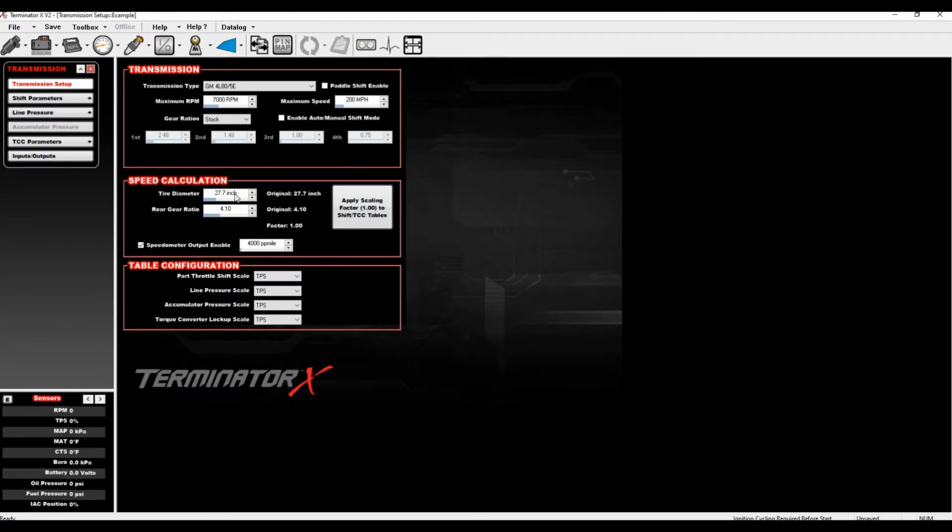So a 275/60, if you multiplied that by 0.6, or it's really 60% of the 275 width of the tire, that will give you the sidewall height. So two sidewall heights in metric, and then you convert that to inches and add your rim diameter, and that should give you a rough overall tire diameter.